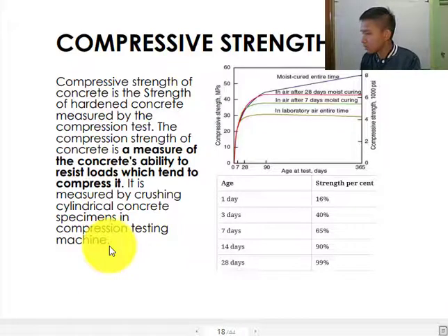Okay, once you are going to pour a batch of concrete on the members, you are going to separate a sample for that, and then that will cure together with the member that you poured. Once it reaches the 28th day, or not just the 28th day, the others test this one before the 28th day, and they graph this. But the important one there is the 28th day strength, because that is what we call the design strength of the mix. That is where we will get the design strength.